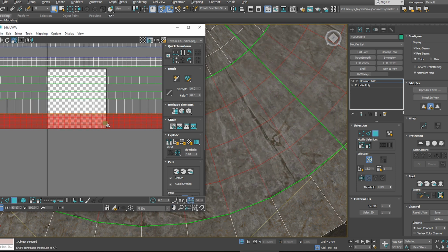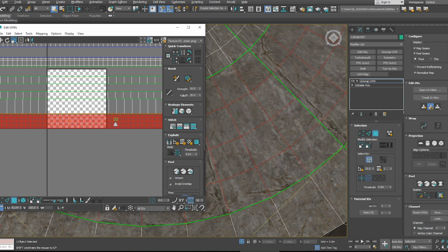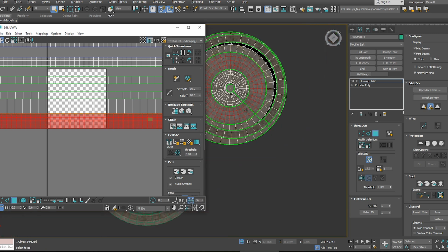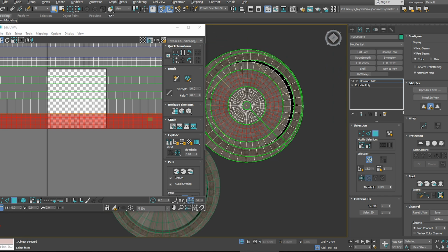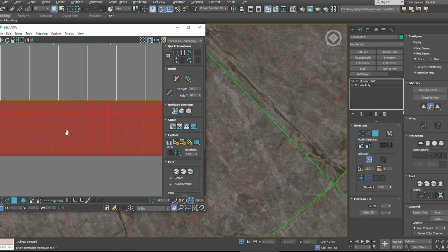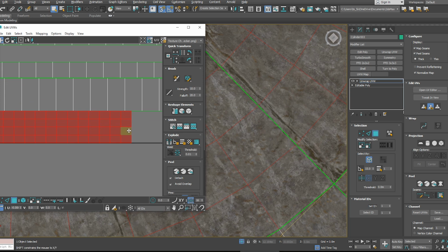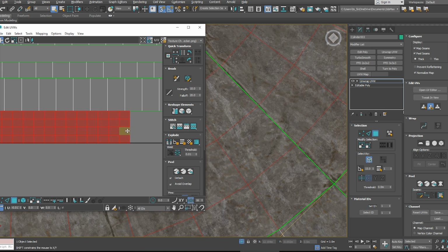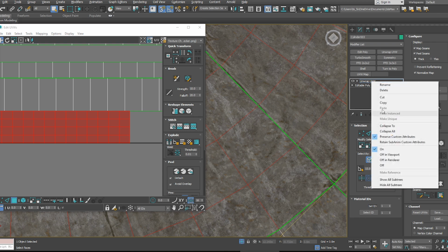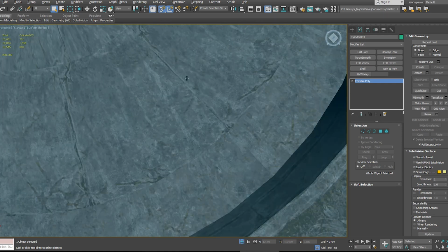And the scale tool can sometimes be a little strange. So I'm just scaling these horizontally because it looked like it was a little bit stretched. And on that, you can see I have the loop here and then the seam. On this seam, I'm going to try and move the texture around until it's actually on a seam like that. And that's a little tip. If you have a seam like this, with a groove with some edge damage, that's going to help hide that texture seam too in game.